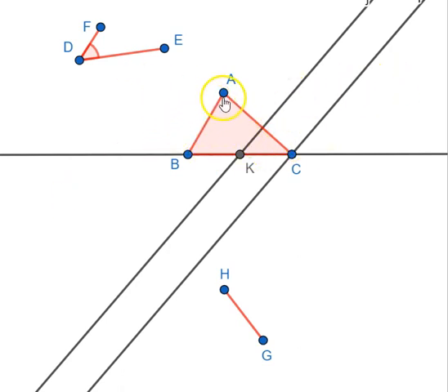So we have to draw a parallel line through A, parallel to this line. How do we do that? If we treat this line and the proposed line, AB will be a transversal through those two lines. We just make sure that the alternate angles between those two lines are equal to ensure that they are parallel.